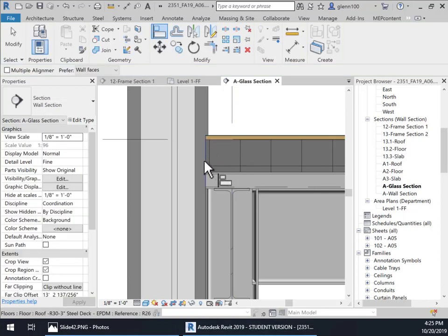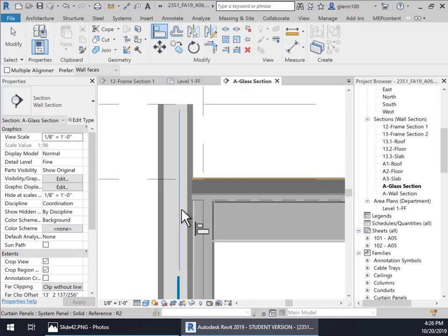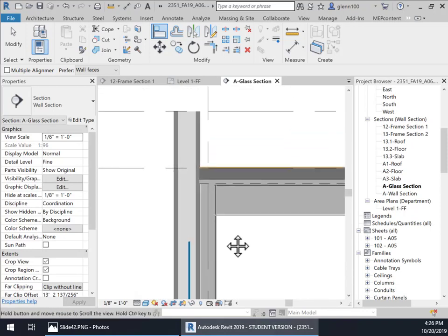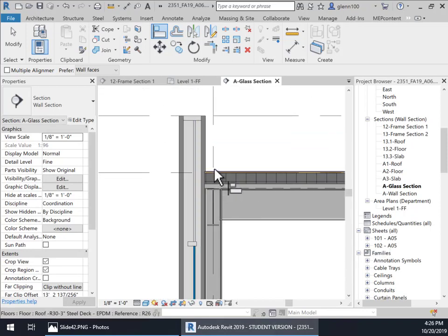So what I wanted to do is line up right here on this edge of my slab, my roof actually, not my floor slab. So I'm going to select that line and then say line this to it. And it didn't move it. Oh yeah, that's right, I remember now why it didn't. So let's go to the first level, because I can't move it by the edge here. I've got to unlock it.